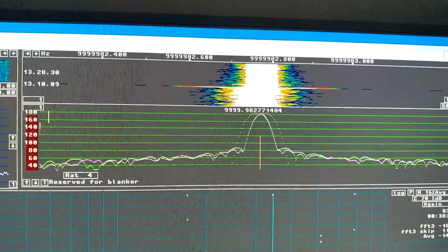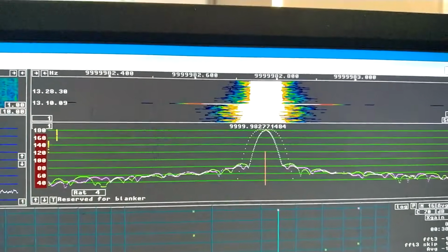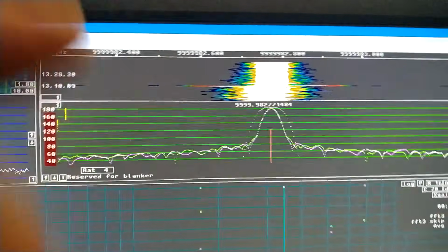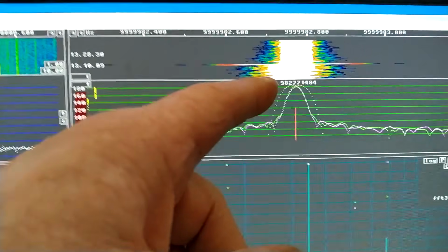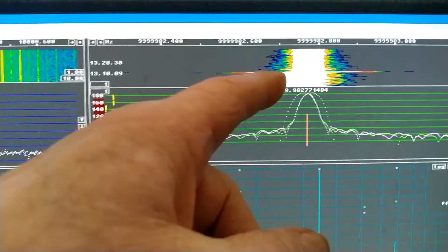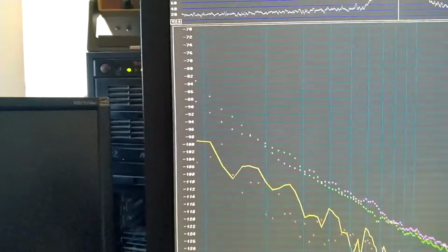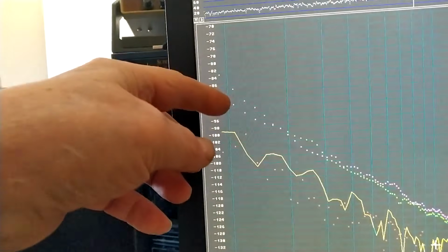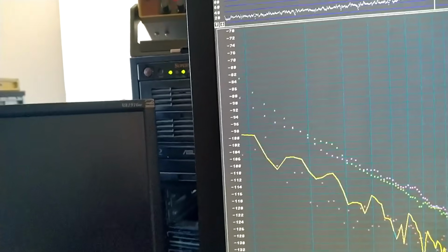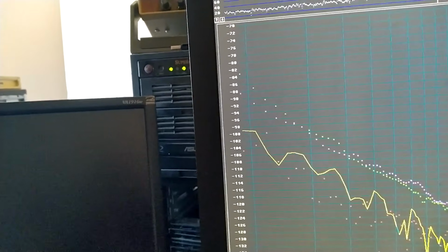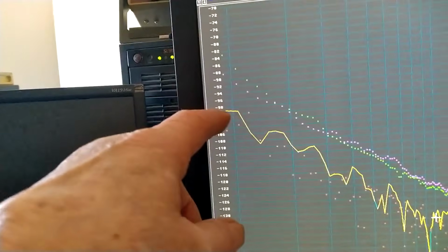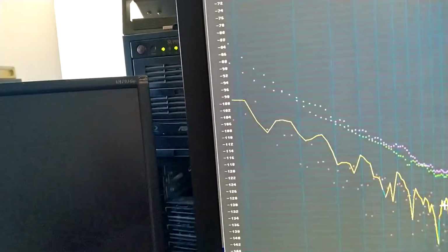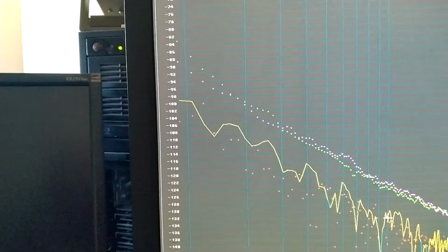Here I have changed the orientation of the reference oscillator in channel 1, and it makes a big difference at a separation of about 0.75 Hertz. And I can see that also here. The difference between channel 1 and channel 2 was before about 10 decibels. Now it is about 4 decibels, which means that convergence will be much faster for the device under test, the correlated phase noise spectrum.